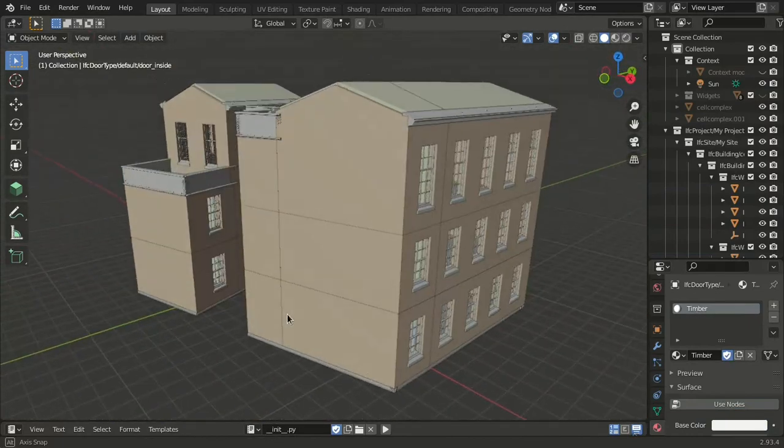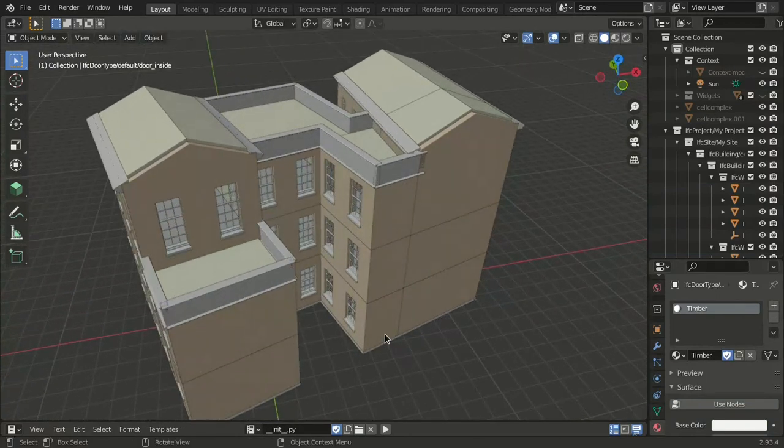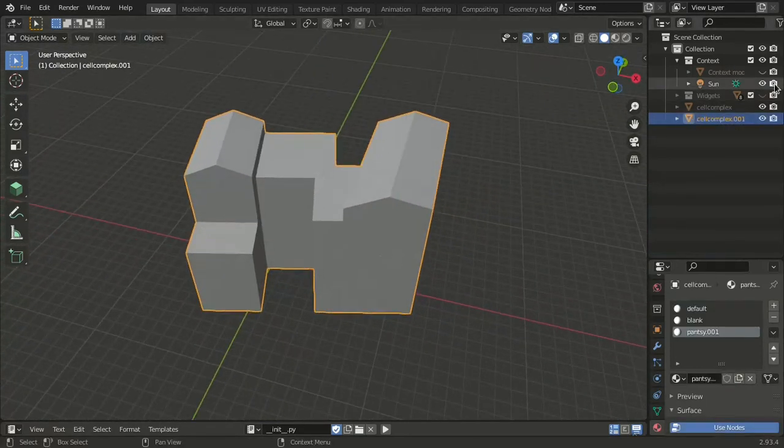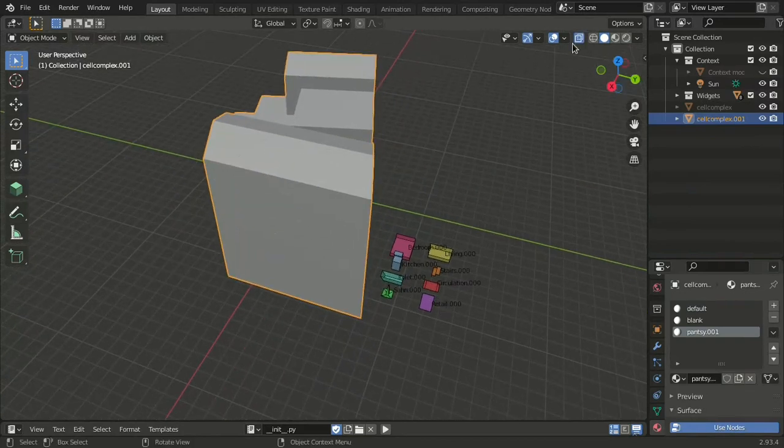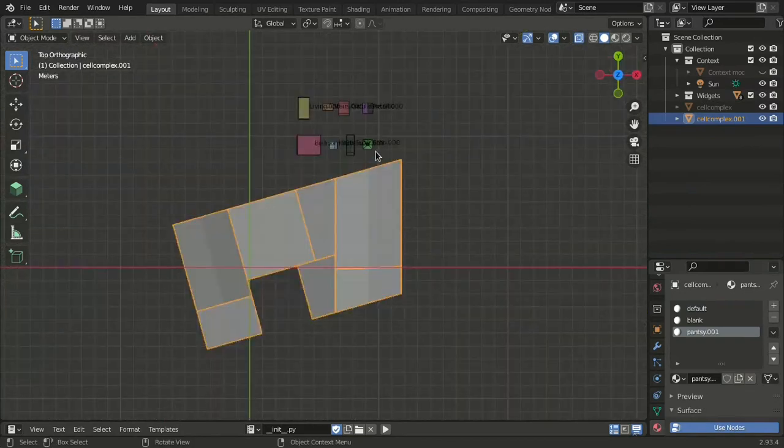By default, the add-on treats all of the Topologic cells as a generic living space, so they get external windows and they get interconnecting doors. If we want to distinguish room types, then I need to tag the spaces as bedroom, stairs, kitchen, retail, etc.